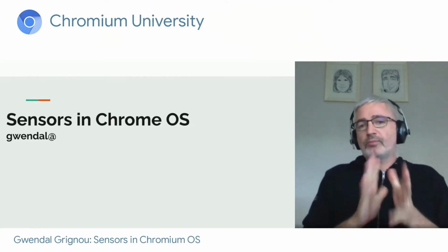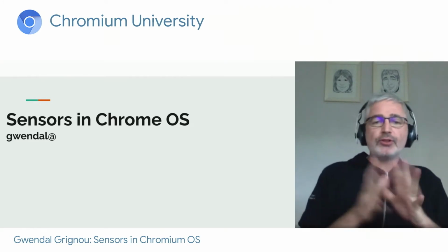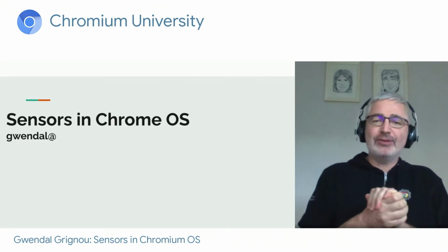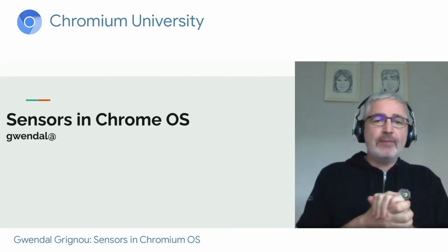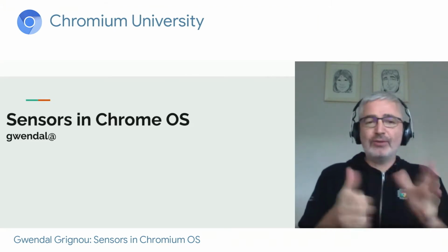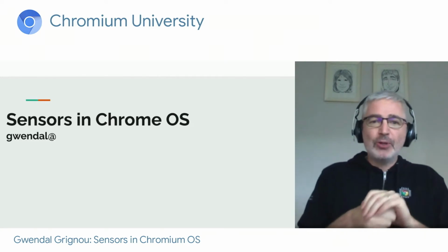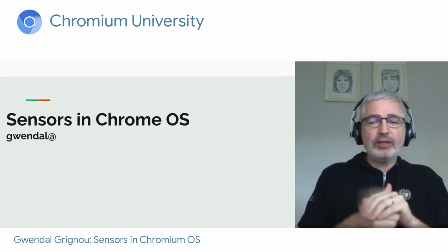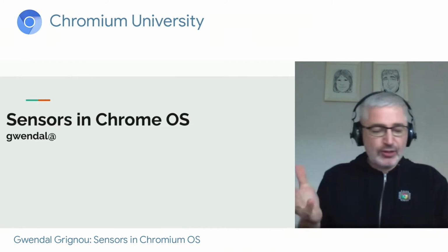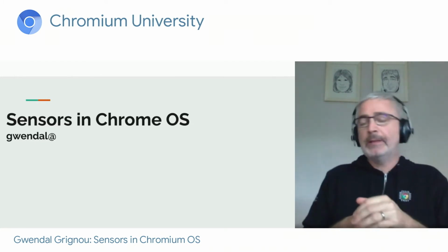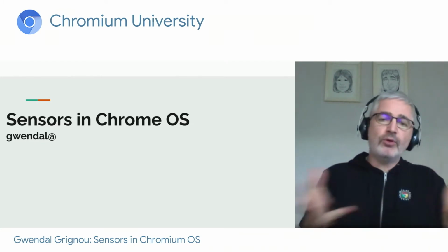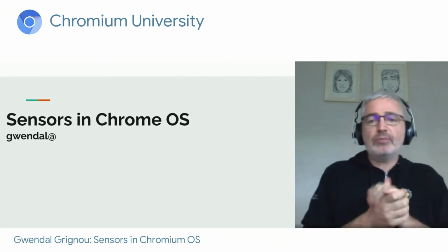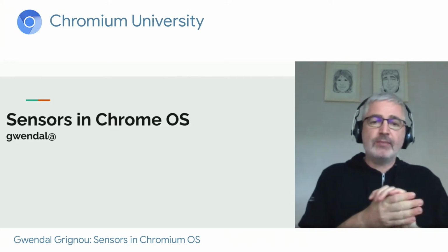I'm limited to those sensors because they are managed in the Linux kernel by the IIO subsystem. IIO stands for industrial I/O. So I'm not going to talk about other sensors like input devices, mouse, keyboard, fan control, or temperature sensors, which are managed by other subsystems.